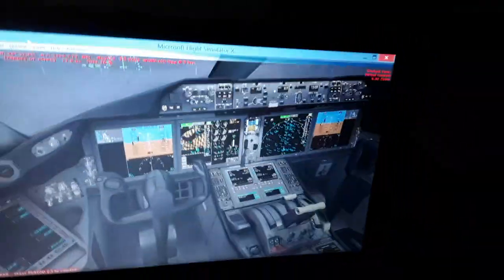Also, you can calculate the closing velocity between our aircraft and the other aircraft. So if we have an incoming collision in the air, it will give us a warning. The TCAS system, traffic collision avoidance system, you can see displayed in the primary flight display and in the navigation display. We're also going to have the EICAS engine indication and crew alerting system display. You'll see the engines